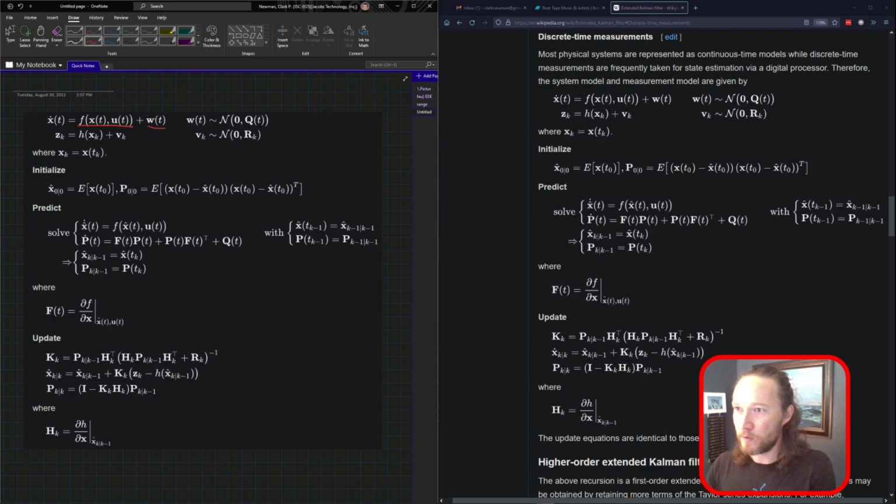This captures what we don't know about the dynamics. And so this process noise is a function of time. It's normally distributed about 0, and it's a matrix whose diagonal is defined by what we call the spectral density matrix. So now that is how we capture both our force model through time and the uncertainty of that force model. We don't have perfect knowledge of gravity out there.